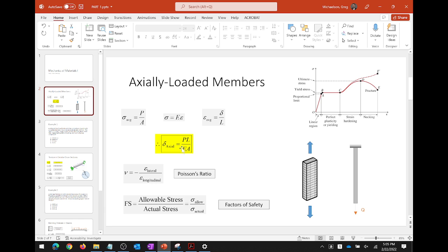So remember in steel design that you have a tension member and you've got bolts going through the member at a given end, right? Remember the U factor, right? Now, what was that for? That was for the fact that at the connection, things are weird. The stresses are sort of wonky, right? But away from that connection region, the stresses kind of even out. That average, if you will, is looking at the average strain and average stress along the member. It is ignoring stress concentration effects that you might get at the end.